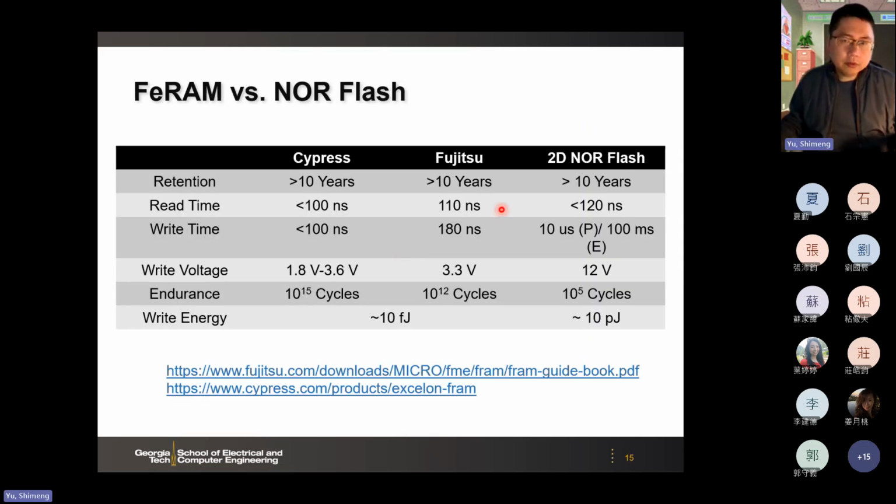Compared to, let's say, the typical FeRAM initial target market is to replace the NOR flash. So for those low cost, like ID card and not high capacity memory, some low capacity, maybe kilobits, at most megabits, and low cost memory products. So here is the advantage. This is from the old generation FeRAM, still sold as separate products.